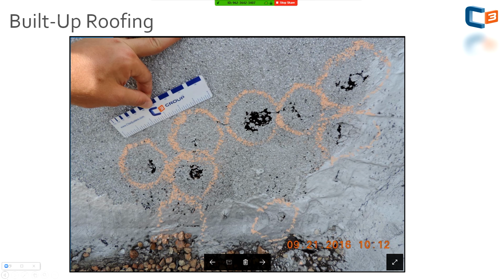So here's an example of that. We have a granulated flashing that extends up a parapet wall. You can see the ballast in the field there. This is a built-up roof. It was a 3-ply, and you can see the hail impact damage on the parapet transition flashing. You can see that black mat come through, right? Similar to shingles, you have the granules pop off. This had an aluminum coating over it as well for UV protection, but you really see that contrast. So, easy hail damage, right? You see the one on the furthest right, right here. That's basically a bruise and it actually punctured the flashing.